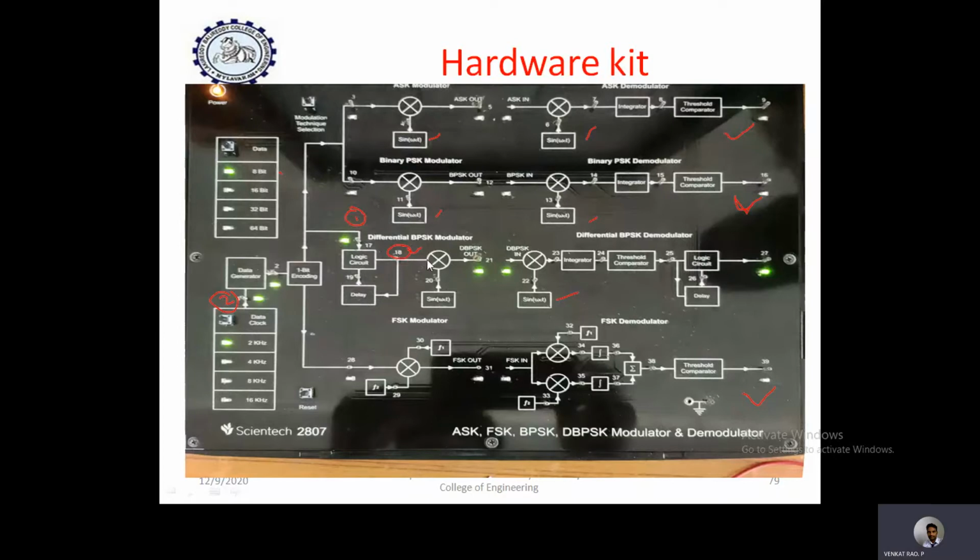That differential data is connected to the general PSK block. The general PSK block, just by multiplying the carrier signal, will generate two phase-shifted waveforms of the modulated signal. That is considered as DPSK. The same demodulation can be observed directly here. Of course, here a coherent carrier is used, but generally DPSK is used for detecting signals in a non-coherent way. Now let us see the experimental analysis.